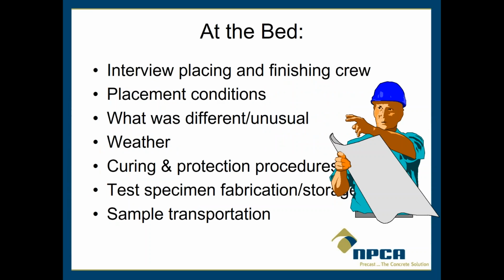And then at the bed, the placing and finishing crew, talk to those guys. Again, they will often notice something different: placement conditions, what was different or unusual. Many times I ask the question, what was different about the concrete on this day, whatever the problem might have been? And almost always the initial answer is nothing. But then after a little more conversation, we get to maybe what appear to be some small things. If they notice something different, then that's good to note.